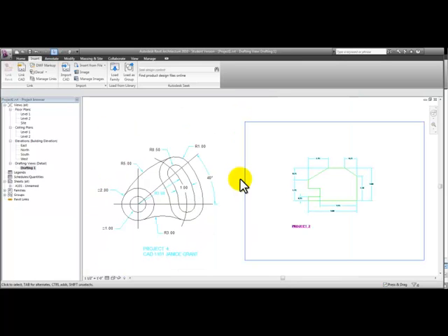It is suggested that when you import CAD details or even link the CAD files that you consider taking out the text, hatch, and dimensions, because when you bring them into Revit, they may not be consistent with the standards that you've established in Revit.